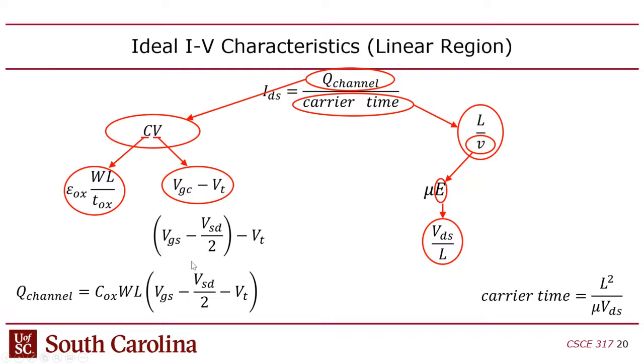Like I mentioned last lecture, I've never really been very clear on why you have to subtract the threshold voltage from this voltage, but that's the only part about this that's kind of always been unclear to me. But obviously the channel voltage is pretty clear, but you have to back out the threshold voltage from that when you do the calculation. Now, as I mentioned, though, the threshold voltage is a constant, generally speaking, for a given fabrication process.